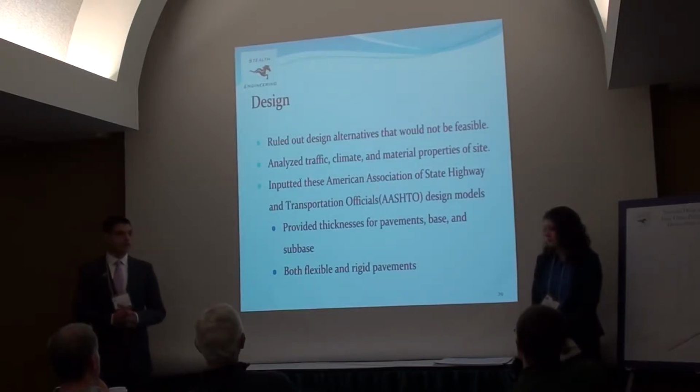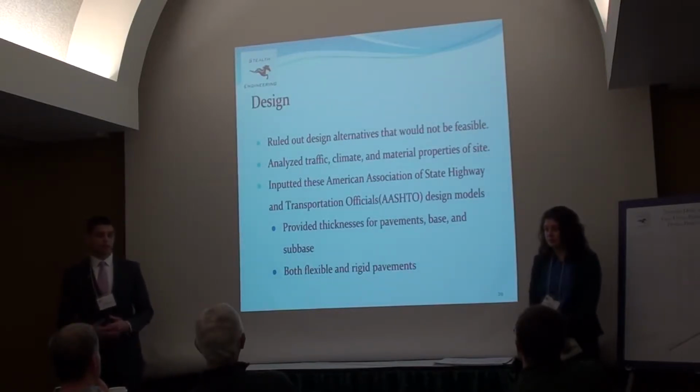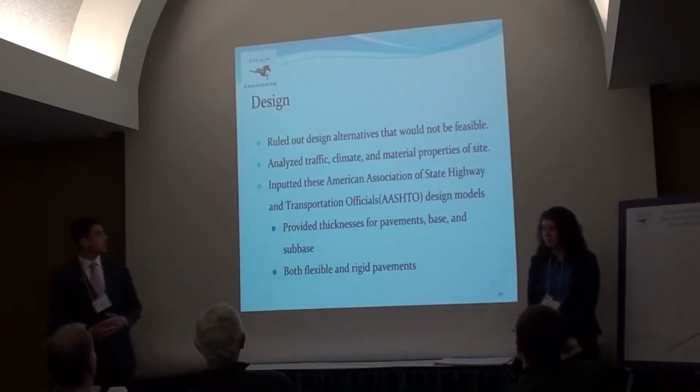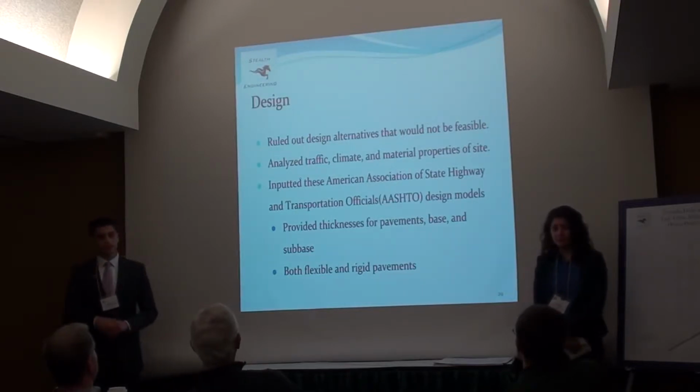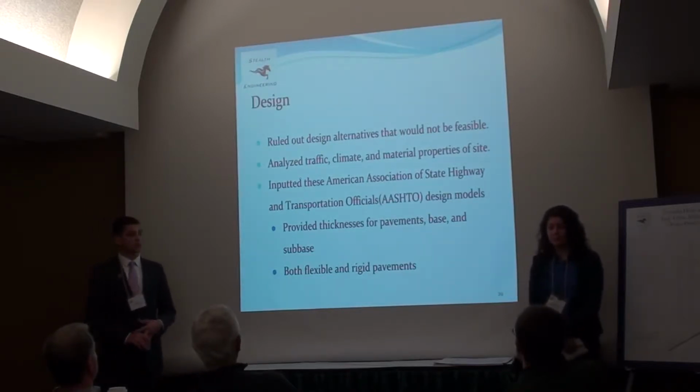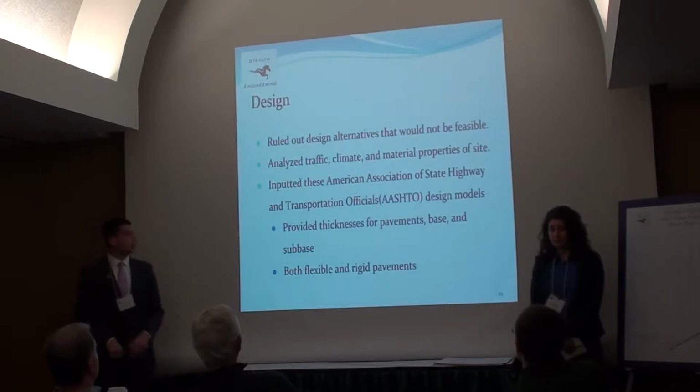We felt that concrete in the neighborhoods wasn't feasible. It would be too expensive, and the roadways did not experience enough truck traffic to warrant concrete construction. The next step was to analyze the traffic, climate, and material properties of the site.